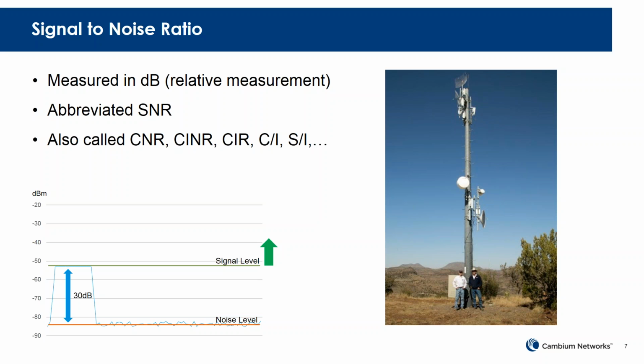Sorry, as a follow-up, will the Cambium products that we offer, are they designed to adjust this power ratio? They do adjust, so that's kind of a complicated question. Typically for outdoor use, you set the downlink transmit power, and that's kind of a static power. In general, what you want a lot of times for outdoor use on the downlink is as much range as possible, and so you set the max possible power.